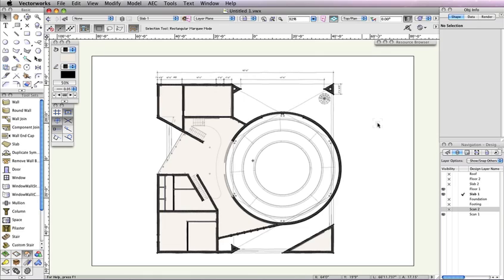Therefore, instead of using the floor command as we did before, we'll create a sweep, since this portion of the floor is cylindrical. To create a sweep, you must first make a profile shape that will sweep around our defined axis point. Additionally, to make things easier, we'll use Floor 1 Scan as a reference to create guidelines before we perform the sweep. First, select the 2D Locus tool from the basic tool palette.